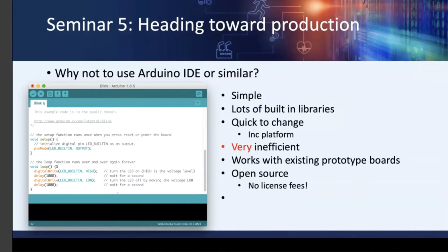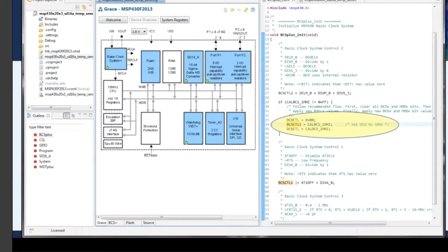Now, this sort of implementation requires such low level access to your memory and to the way the instructions in your program are being executed, which is just not possible with the Arduino programmer because everything is kind of abstracted out. But with something like IAR or Code Composer that Ian currently has showing, you can mix assembly language and C-level language. You can look inside your registers. You can have a look at your memory block. So you have much finer control over that low level access to your memory, and those programs can be implemented much more optimized.